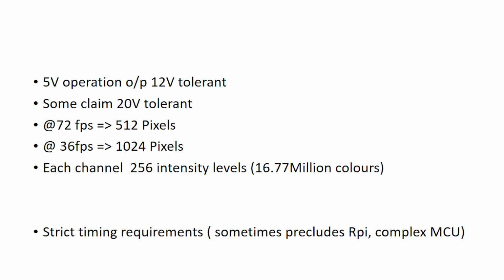There are strict timing requirements. Now this is really important. These things work by a pulse that is to be a certain width. I'm about to go into the theory of that. But that pulse has to be there, and it has to be a certain width at a certain time. Things like Raspberry Pis and ESP32s and PCs, for example, have got multiple threads all running at the same time.